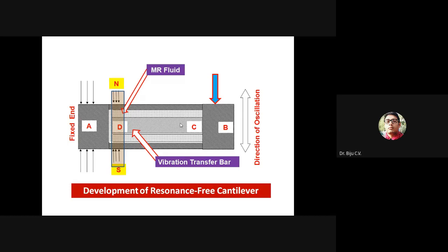But if you are brilliant, if you want to take some challenge, then you can go for tuned mass or tuned frequency structures, where you are giving freedom to the operator. You operate at any frequency. The system is stable because we are not depending on what the operator is doing. We are depending on the inherent property of the structure and also the tunable mechanism incorporated into it. So there is no need to put this type of resonance-free mechanism in all the elements.